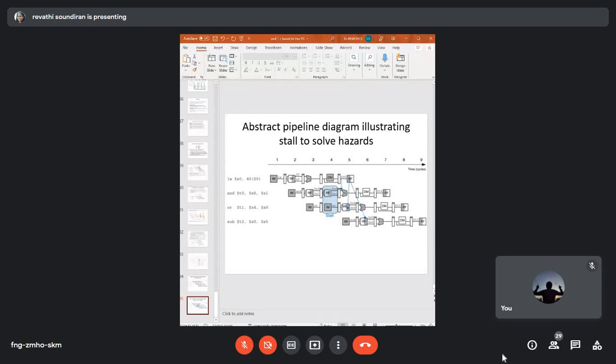So in the fifth cycle, the result can be forwarded from the write back stage of your load word to the execution stage of your AND. And in this cycle 5 only, the source register of your OR is read directly, with no need of forwarding. So here there is no need of forwarding, but here you need forwarding. Yes, you got the point?